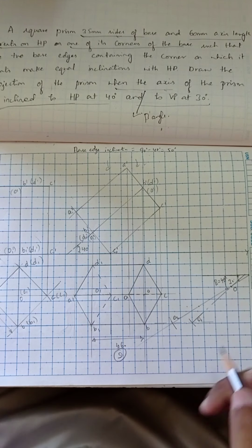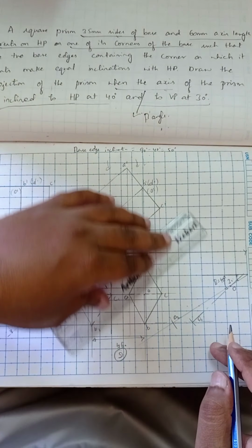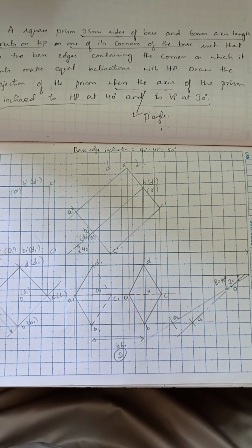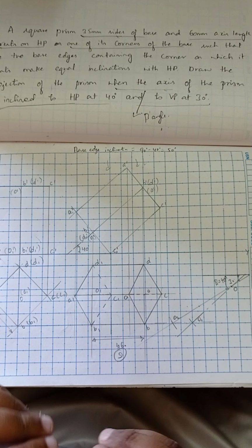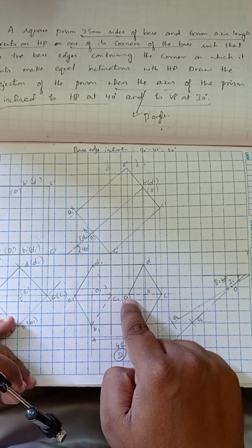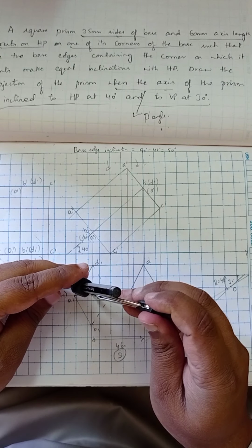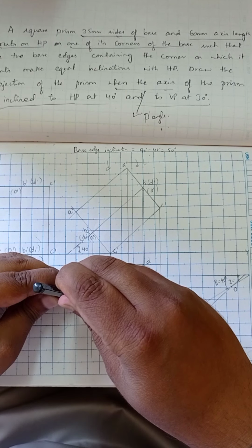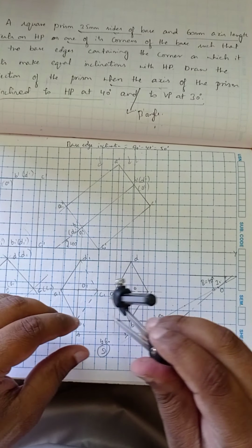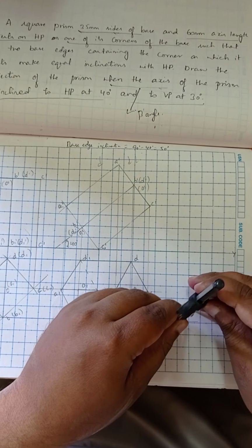You can see that we have already drawn the O1 line here. So we have to transfer this diagram. I will extend this line a little bit. Now using the arc method we can transfer the diagram. On this line we already have A1, O1, C1, A, O and C. So we can cut the arcs by measuring with the compass from O1 to A1, and similarly O to C1.